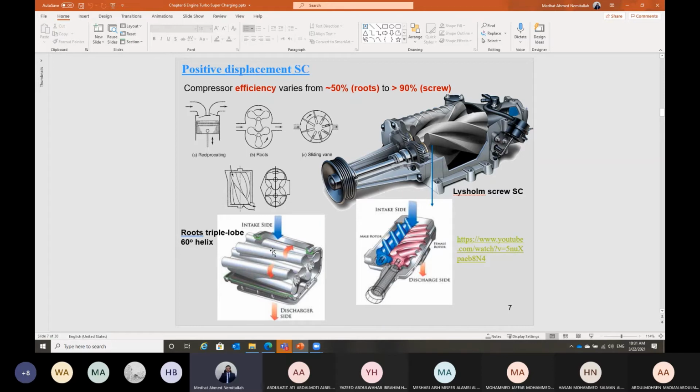It can be a helical design. The helical design is to have the helix. We have a helix in the flow direction. The flow is coming here at the bigger area between the roots, and it is a helical shape. So we reduce much the volume, or the area between the two blades is much reduced. So it can result in a much greater increase in the pressure.